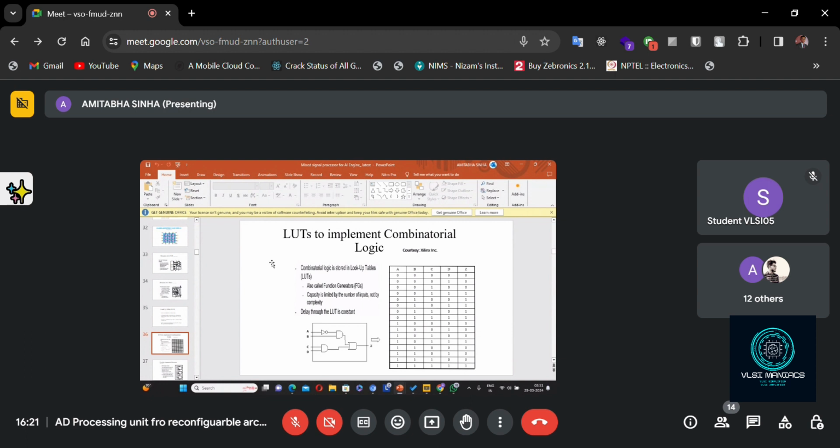Now it is D, after that it will be something else. So while it is working, some bit stream can be downloaded to make the required change. This is called on the fly reconfiguration. So some part is still working, but some part is getting configured. These are very important for many high-end applications.